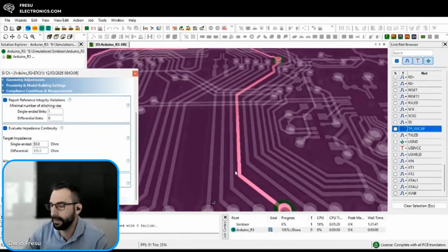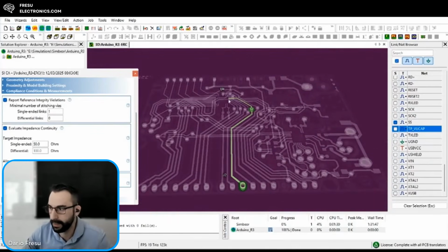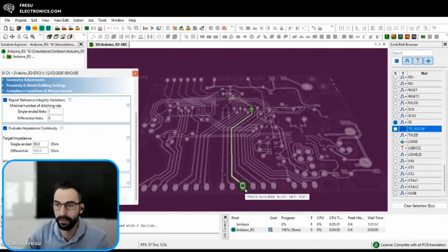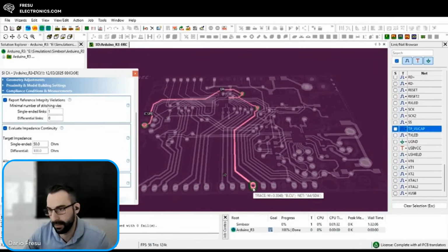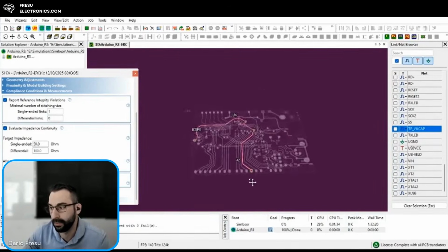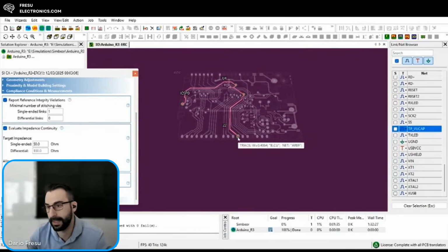So for example, if I have the coupling of the signal between this net and this net, what can happen here? I'm trying to propagate a signal from this net, then it couples to this net, and maybe in here I don't have a cable connected to the connector. Or maybe in here I do have a cable connected to the connector, and maybe this cable is 2 meters long. So if a signal can couple from this net to this net, then a signal coupled to this net can propagate through the cable that I have connected to this port and to this particular pin. And this cable serves as an antenna structure for the signal.